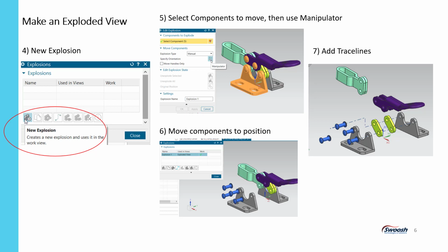Now, sometimes it's more illustrative to see something that doesn't work the first time, so I'm going to leave the video as is. So when you forget to do the same thing I did, we'll have that memory jog and say, oh, I just need to go back, re-edit my explosion, move things over a little bit, and then continue and add the trace lines. If you have trace lines already in place, that's fine, they will update.